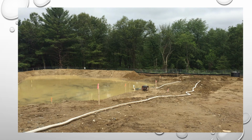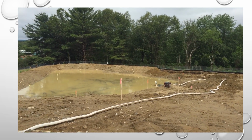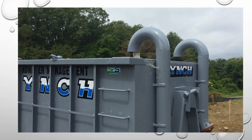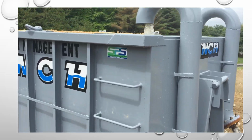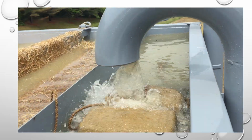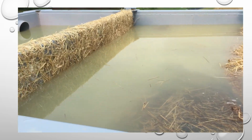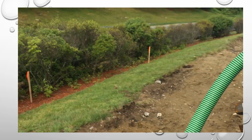Tanks are a really great option as well. We'll do a couple tank examples in the next presentation, but here they're pumping out of this turbid basin. The flocculant is not being dosed in the line, but it is right here in the tank itself. So the water is flowing into the tank. There's some turbulence there, some mixing, some reaction. Normally you'd want to have a little bit more mixing and reaction after that to flocculate it, but you can see the water starting to settle a little bit there.